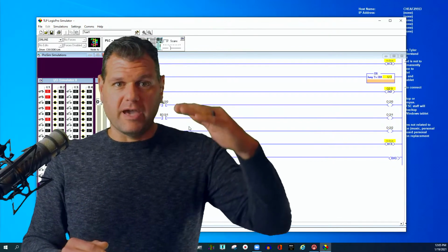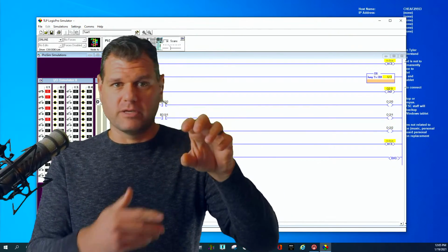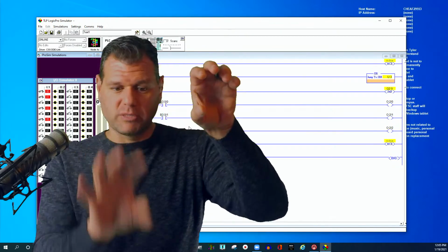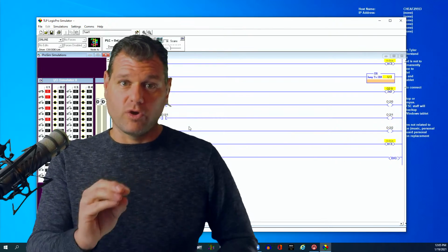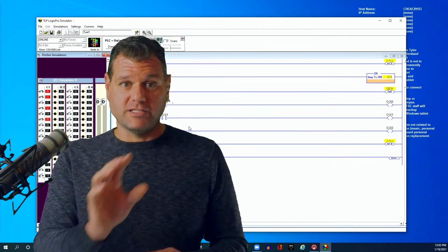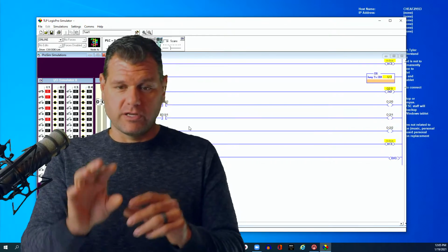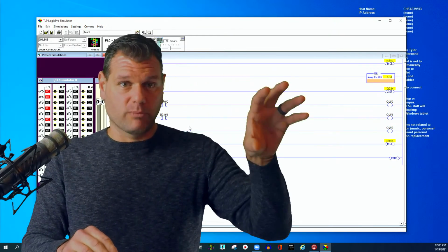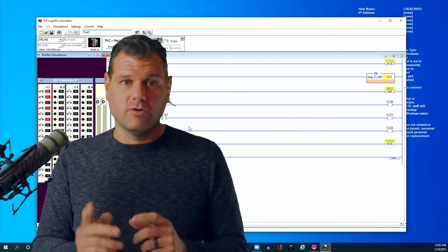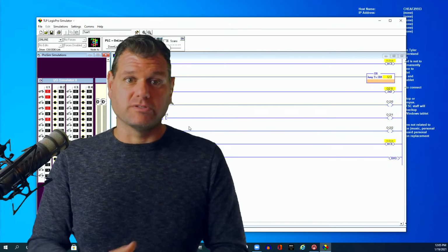Let's say that it scanned it through its normal scan cycle and it said that something was off. Some kind of input was off, encoder, optical, something. These things are changing within milliseconds, right? It goes to read the program, and it reads through all the rungs, and on one of the rungs it says immediate input. What that means is I want you to go back to this input and check it one last time before you go further. So it stops scanning, goes and checks that table one more time, just that one bit, and it says, has it changed? Yes, it has changed, I'm going to change my bit now. Or no, it hasn't changed, I'm going to maintain where I was off. Then it's going to continue on and then update outputs and so on.